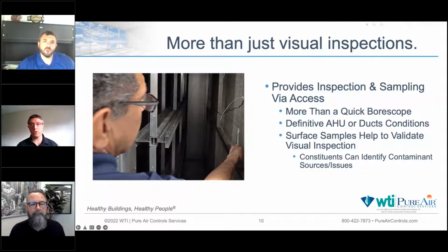It might be related to bypass through a filter, allowing things like pollen grains to accumulate. We also might be able to detect, hey, we do have microbial growth, right? And especially in a healthcare setting, if we detect a lot of that, that prompts us to say, hey, this is a serious concern now. We're trying to avoid HAI, so how do we do that? Let's clean this up. Let's remove that potential source. So absolutely, with the sampling side, we have that.